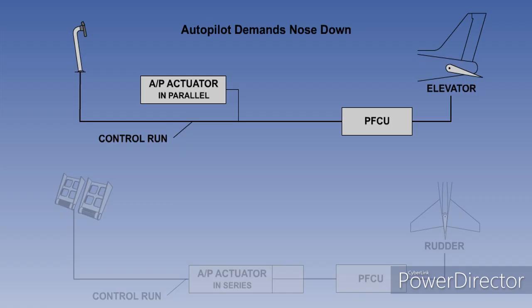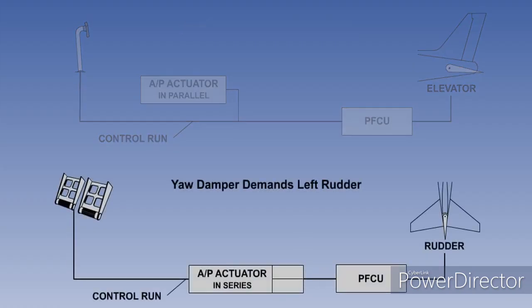Most aircraft with traditional mechanical controls will have their pitch and roll channels connected in parallel and their yaw channel connected in series. The yaw channel is likely to incorporate a yaw damper, which will continually counteract any Dutch roll tendency. This will be fully explained in another lesson. The series connection of the rudder will prevent continual small movements of the rudder pedals. Aircraft with fly-by-wire control systems have different arrangements, dependent upon the manufacturer.